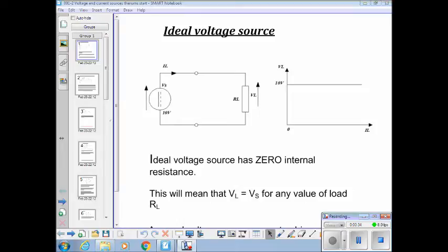If we have a voltage source like this one here, Vs, and that's 10 volts, and we draw by convention a voltage arrow pointing to the positive terminal, so the other end must be negative, we expect the current to flow in that direction. If that's ideal, we would get 10 volts regardless of how much current we drew from that. So we're making an assumption that whether we draw 1 amp or 1,000 amps, we're still going to get 10 volts out of the source. That would be what we'd get if that was ideal.